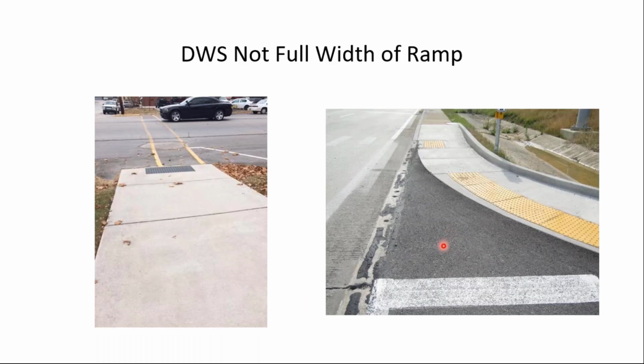And here I'm not sure what happened. They made use of detectable warnings where the curb was missing here and at the crosswalk, but the curb is also missing in this section right here. And so there needs to be detectable warnings throughout this location. Again, it's possible someone with a vision impairment could walk into the street without realizing it.